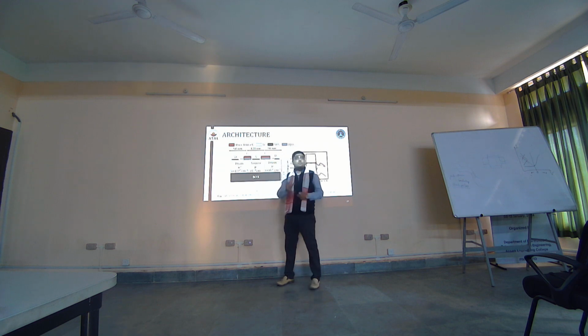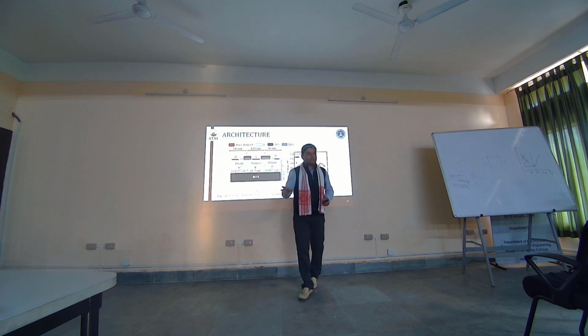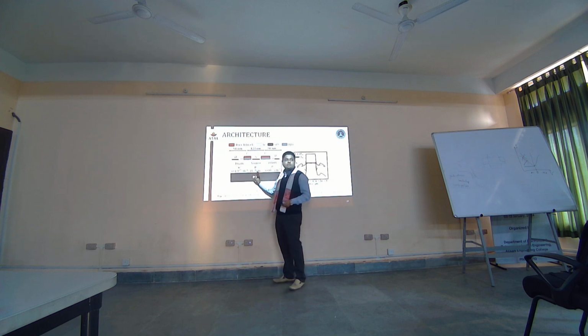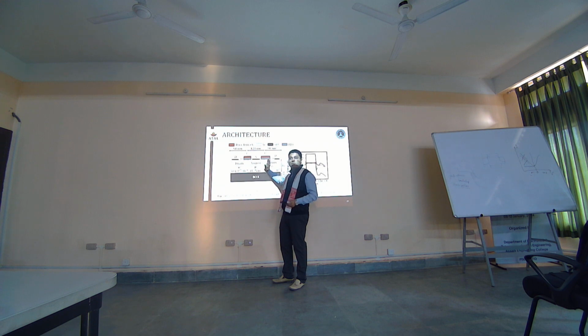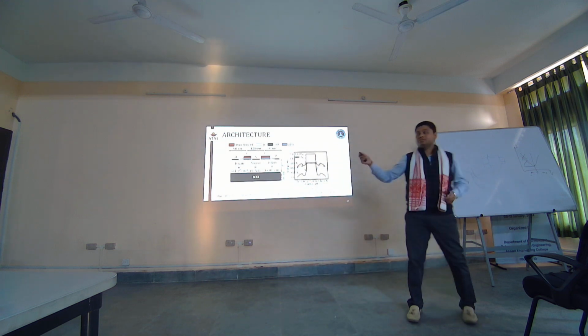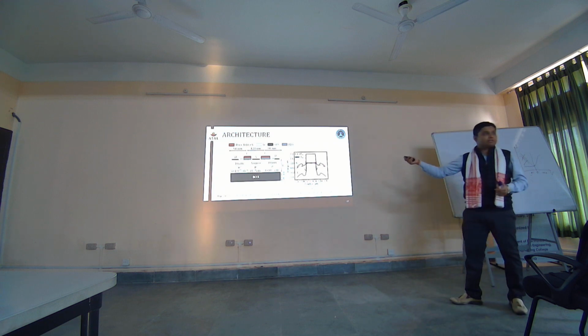Now here you see your source is common to both the drains. So basically both the junctions are reverse biased, so that you can have the Zener effect in your device. If you split it from the middle, this is a very symmetric structure where you have two PN junctions. And if you want to induce reverse bias tunneling in PN junctions, you apply reverse bias between the two, and then you can have the creation of this tunnel. Okay, so this was the second motivation why we went for this structure.